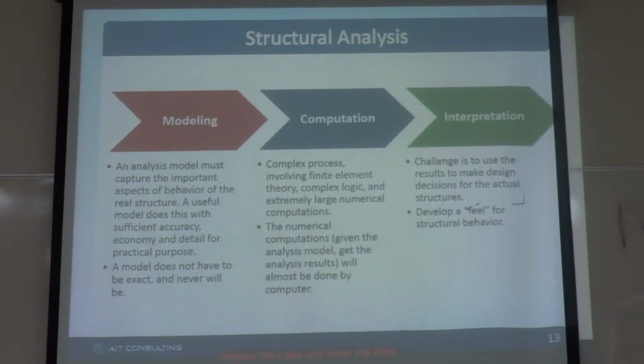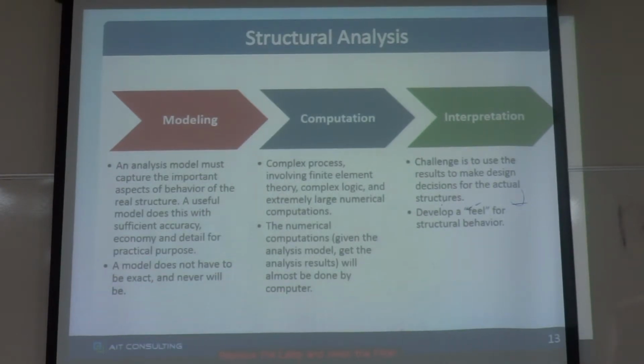If you see the value, let's say a bending moment diagram, and in the bending moment diagram you have 500 kilonewton meter, for example, you can feel whether that value is big or not, or whether it is manageable or not. That kind of feeling you have to develop, the feeling and skills to interpret the results.